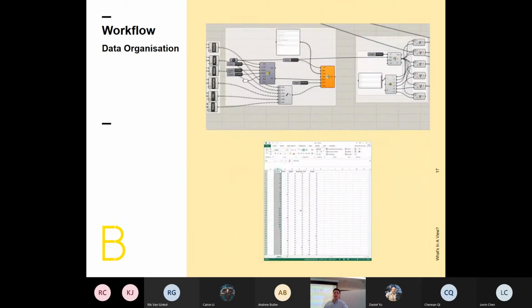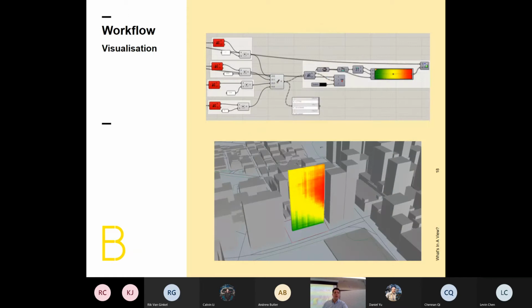Because of the massive amount of data, I had to try and find a solution to store it, because when I stored it in the Grasshopper file, it became massive and it would crash very often. So writing it to an Excel file, then reading it, provided a good solution using test geometry. When using the real 3D geometry of the city of Sydney, latency was incredible. It would take 5 minutes just to unplug a component or plug a component in for it to just run again.